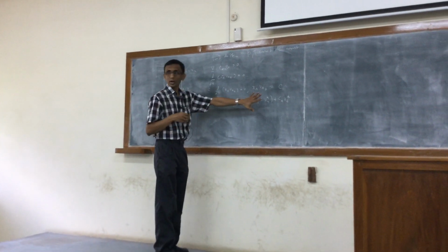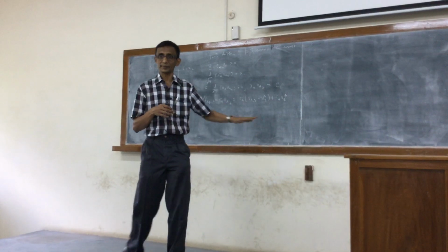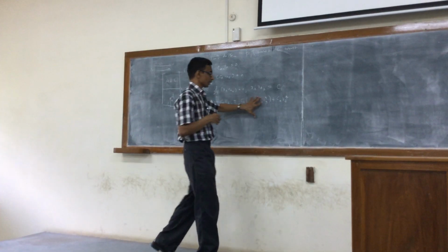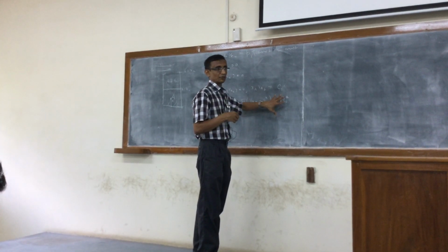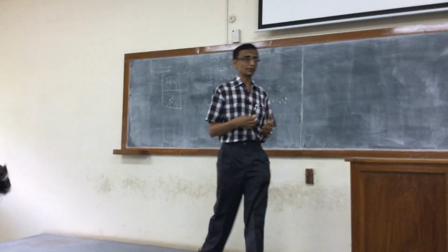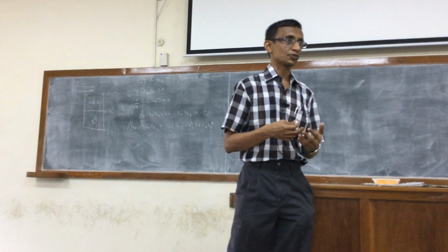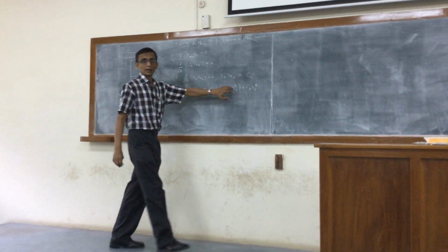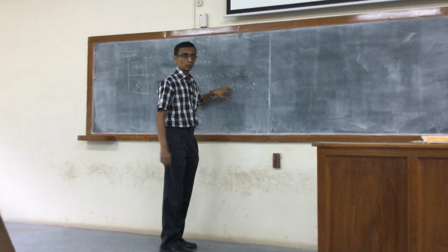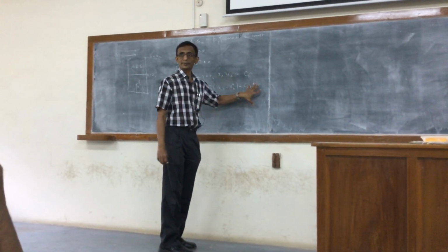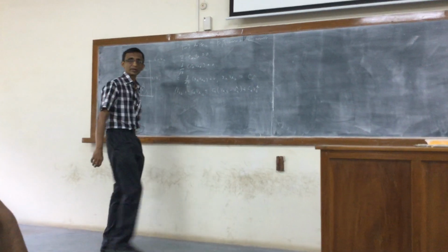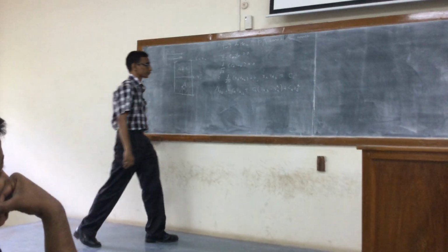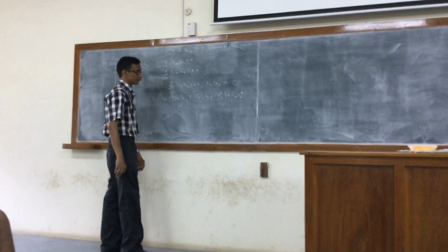Anyway, you should not have any doubt with this expression. It's just a definition of N_A, the convective flux. It's often regarded as a sum of a diffusive flux plus another convective flux which involves the average velocity. The convective flux of A can be decomposed into two. One is a diffusive flux plus the remaining, which is also a convective flux but calculated using the molar average velocity. So this is straightforward from just the definition.